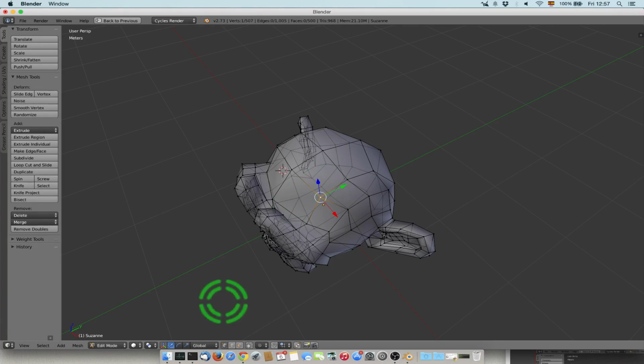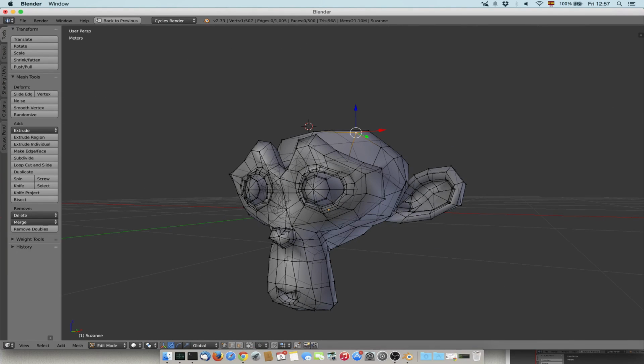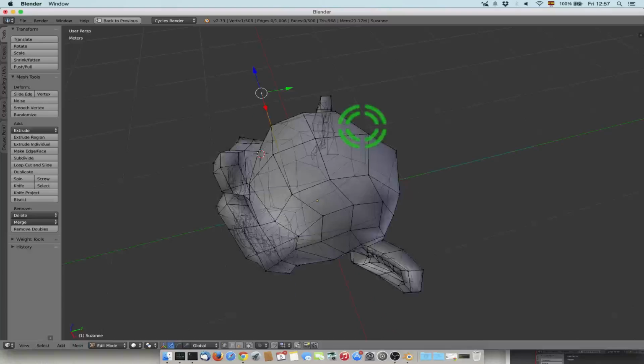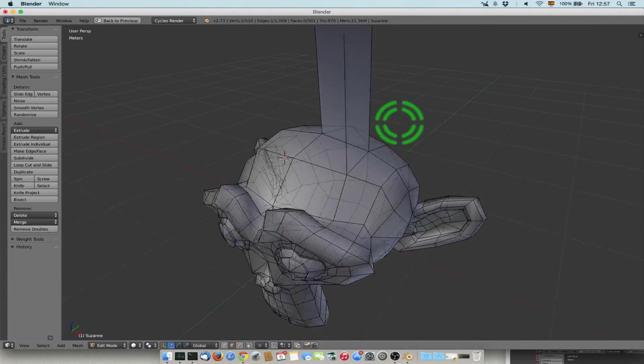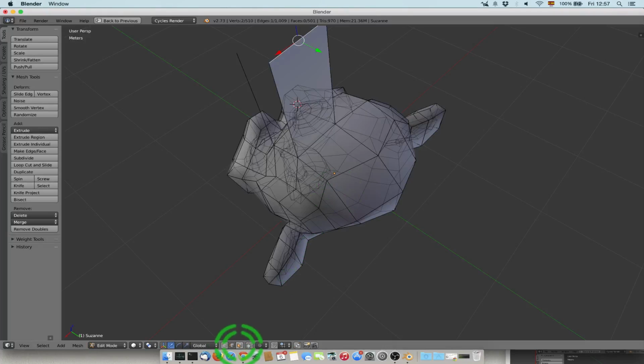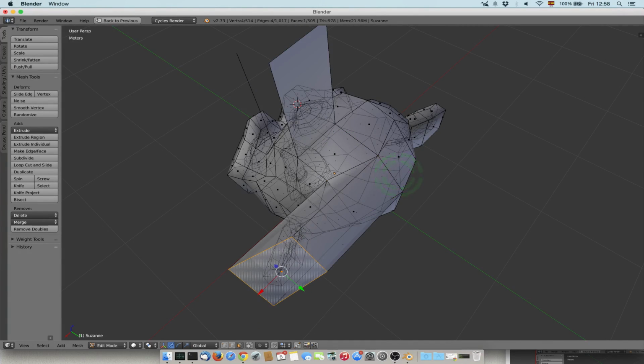Now, one more thing that you want to do, and you can do with the vertex, with the edge or the face, is extruding. So you can extrude the object with this. If you extrude from the vertex, you extrude with E, and then you decide the direction. So again, for example, Z and 1 is just this. If I extrude this, extrude Z 1, it's a face. If I select a face and I do extrude Z 1, it has a volume.